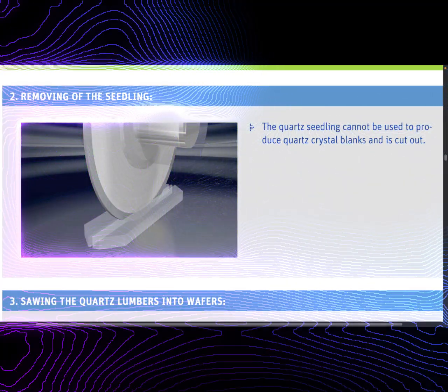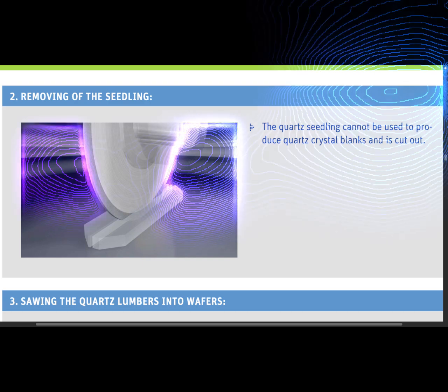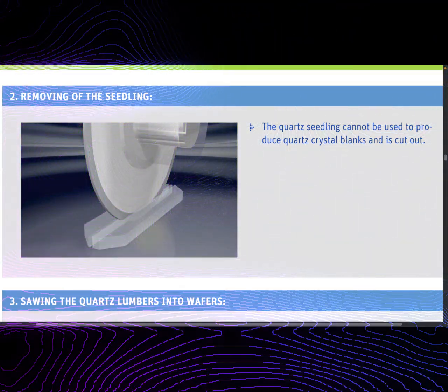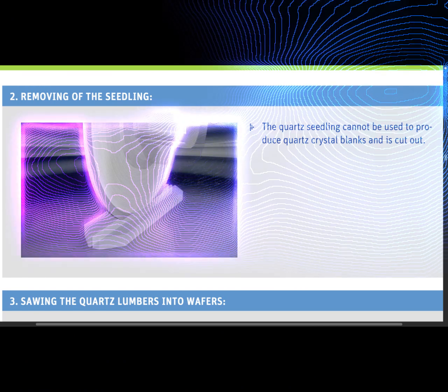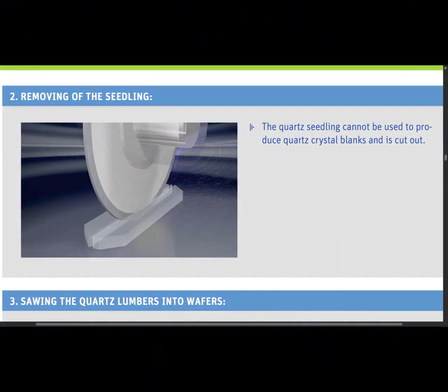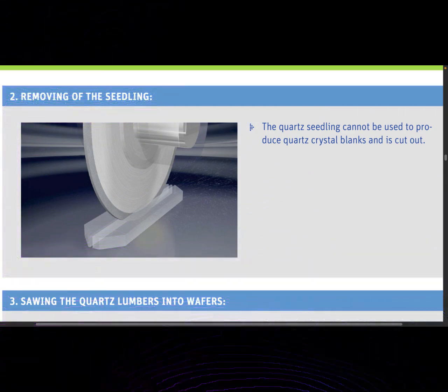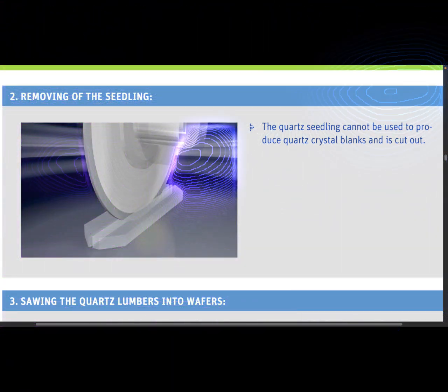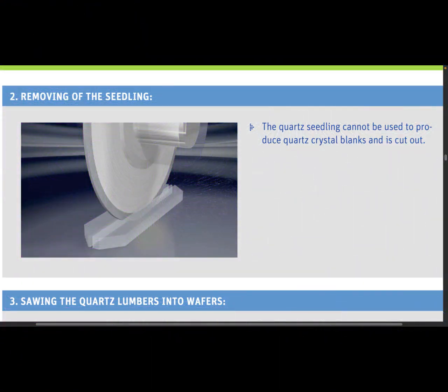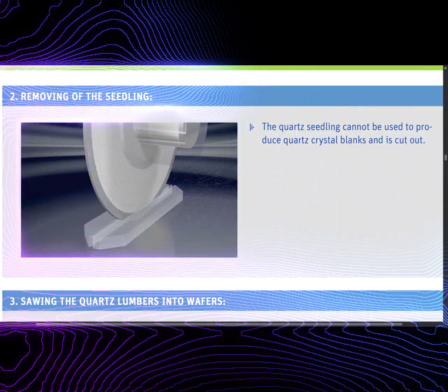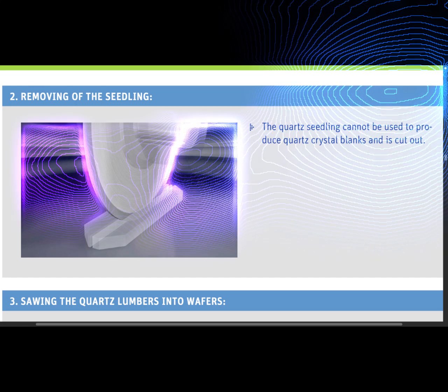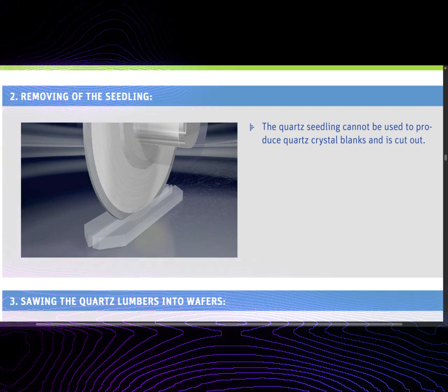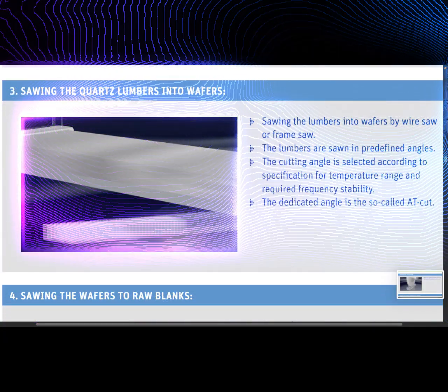Voltage-controlled crystal oscillator. A voltage-controlled crystal oscillator allows the frequency to be adjusted or pulled within a small range by a control voltage. These are useful in RF and audio frequency circuits, for example, as they allow the system to adjust the frequency to match an incoming signal, compensating for a small difference between the clocks.